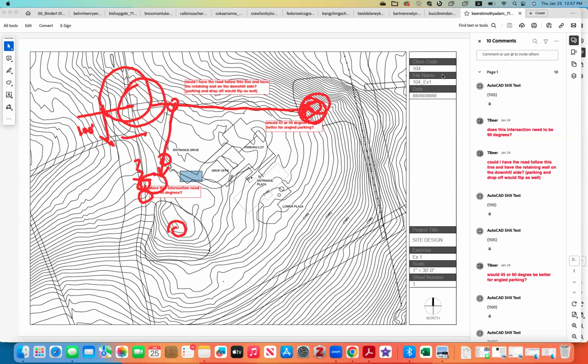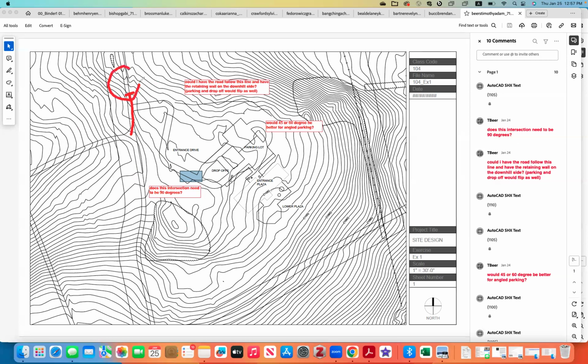Yeah, let's opt for this. Let's measure for it to be 100 foot and see where it lands. If it lands in this area, definitely no, because this is getting really steep. And if not, if it's about in this area, then we'll say, okay, let's try it. Then we have a different entry drive, but that connection, I would never do that, just because it creates a lot of chaos for both parking lots.